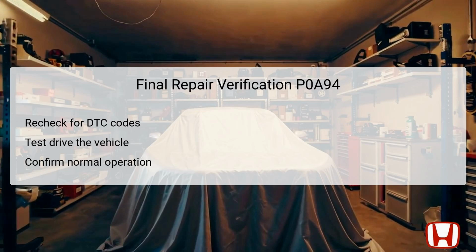Following this check, take the vehicle for a test drive under conditions similar to when the DTC was originally triggered. Monitor vehicle performance during this drive to ensure systems are functioning normally and that the DC-DC converter is operating effectively. After the drive, it should be verified that all electrical systems respond appropriately and maintain stable performance levels. If all checks return normal results, it indicates that the troubleshooting and repair process for DTC P0A94 has been successful.